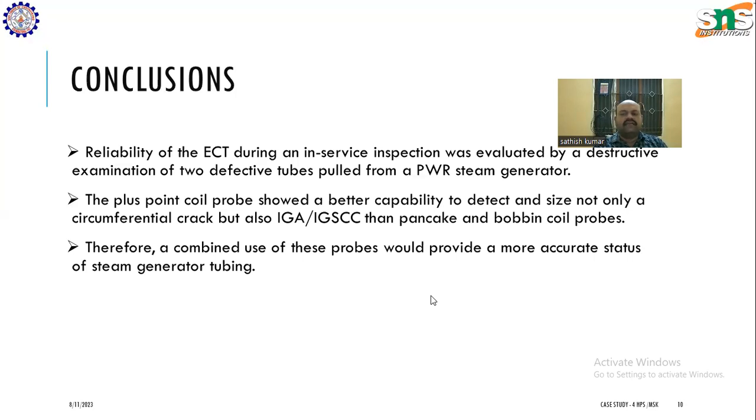We have taken a steam generator tube from a nuclear reactor to find out the defect or discontinuity in the tube. Using eddy current probes, it is measured and the impedance shows a difference where there is a defect, and this defect is again seen through various analyses like SEM, and it is confirmed that there is a defect. This method is very interesting and very safe to use, and when the material is conducting, this method is highly efficient to find out the cracks.